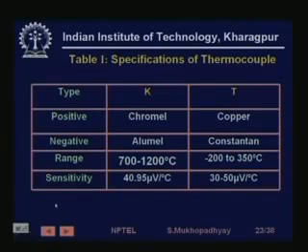They are typically called by some industrial type names like J, K, T, S. So K type thermocouple is a popular one. It's called chromel-alumel. It has got a good sensitivity and a decent range. So it generally measures in this range. Similarly, you can have copper constantan, which has the only problem that the range is lower, basically because of the fact that copper gets oxidized and corroded beyond this, and there is also some variation in the sensitivity. So that means that there is some amount of non-linearity there.